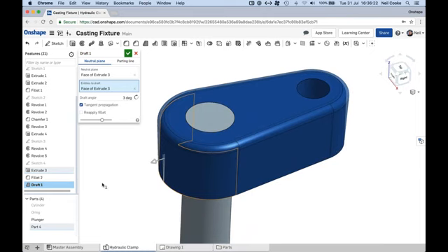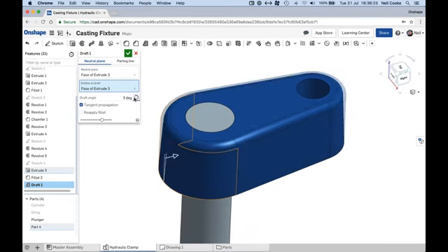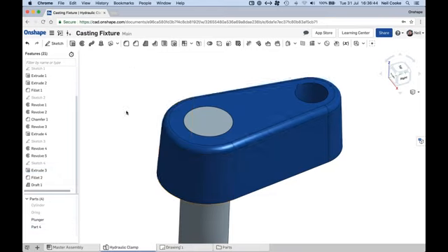It's still being generated after the fact. Whereas in a lot of solid modeling courses you're taught to add your fillets and your chamfers right at the end. You can do it, and in particular, do your draft first and your fillets second. You're a little bit more flexible here in Onshape.